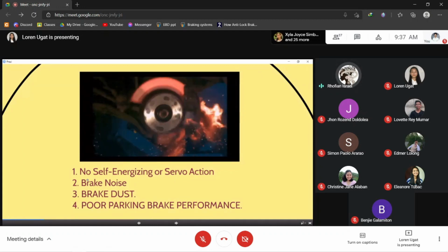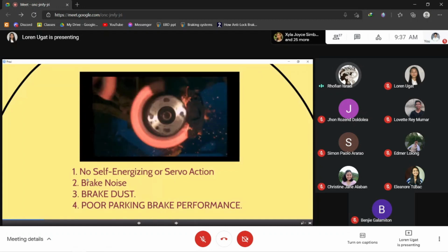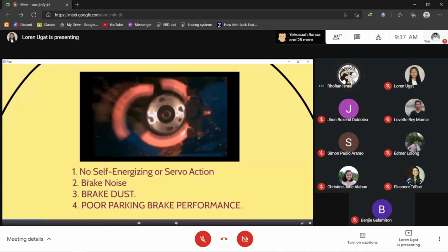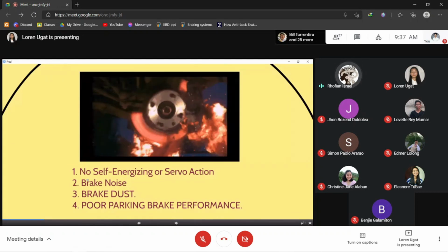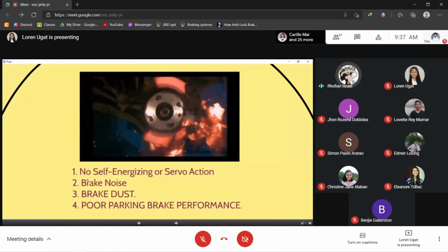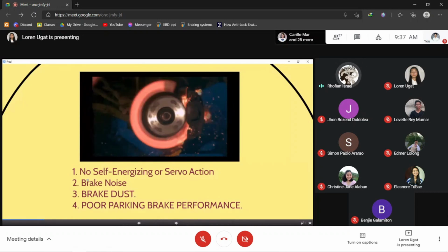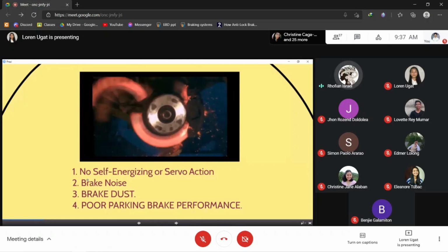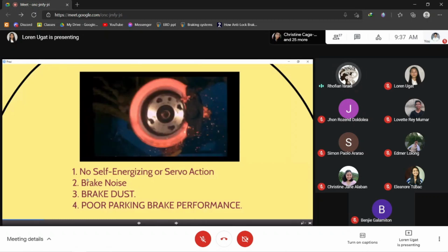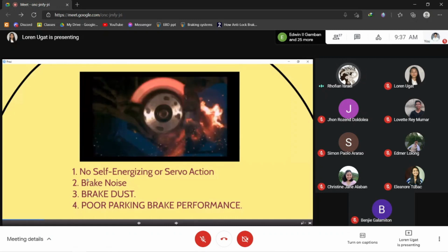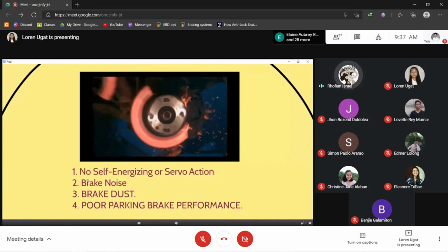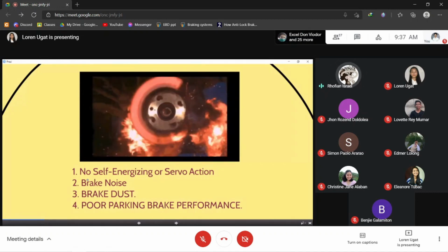And then, another jud po kay ang brake noise. Probably the biggest complaint about this brake is that they sometimes make various squeaks and squeals during a brake application. So, as long as the linings are not worn down to the backing plate, these noises are usually caused by high frequency rattling or vibration of the brake pads. So, now several methods that are used to quiet noisy disc brakes. Kasagaran ganing manufacturers ron use specific lining materials that dampen the vibrations, and most calipers have anti-rattle clips or springs that hold the pads in the caliper under tension to help prevent the vibration.